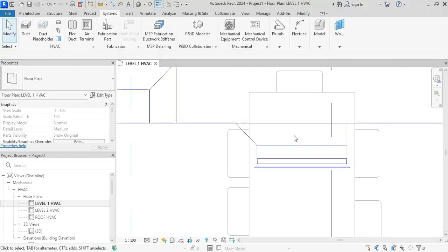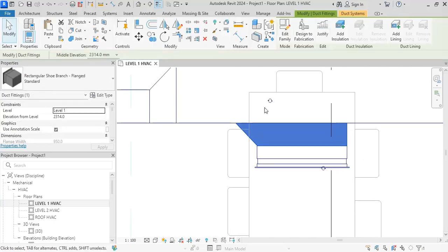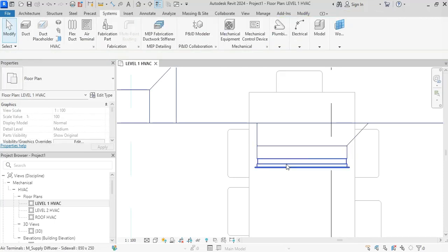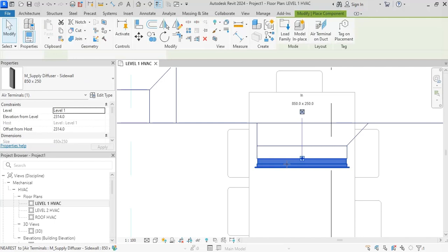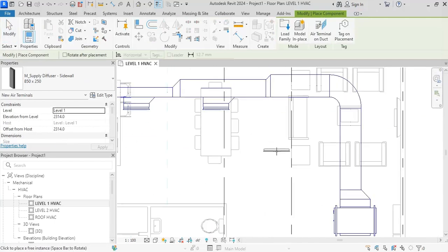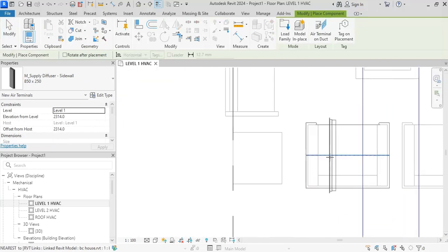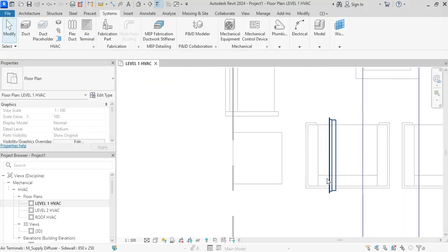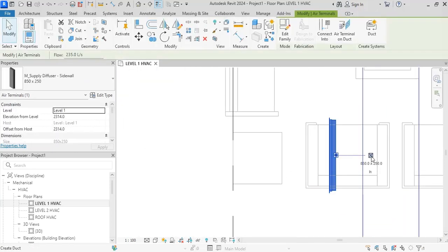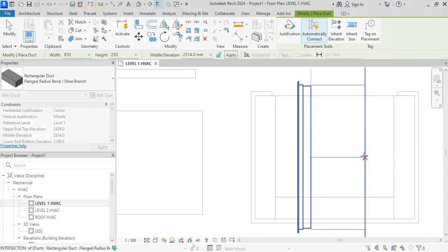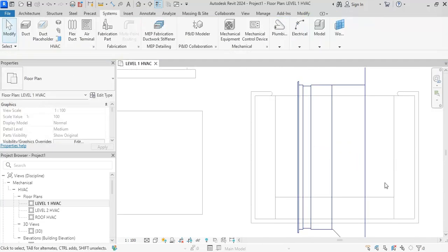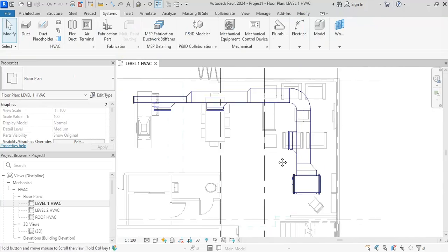And the same issue, I will click the transition, and then this one, and then click on it, CS for create similar, and I press space to rotate it. I want it to be in here. Click here and then drag it. Now the transition looks good.